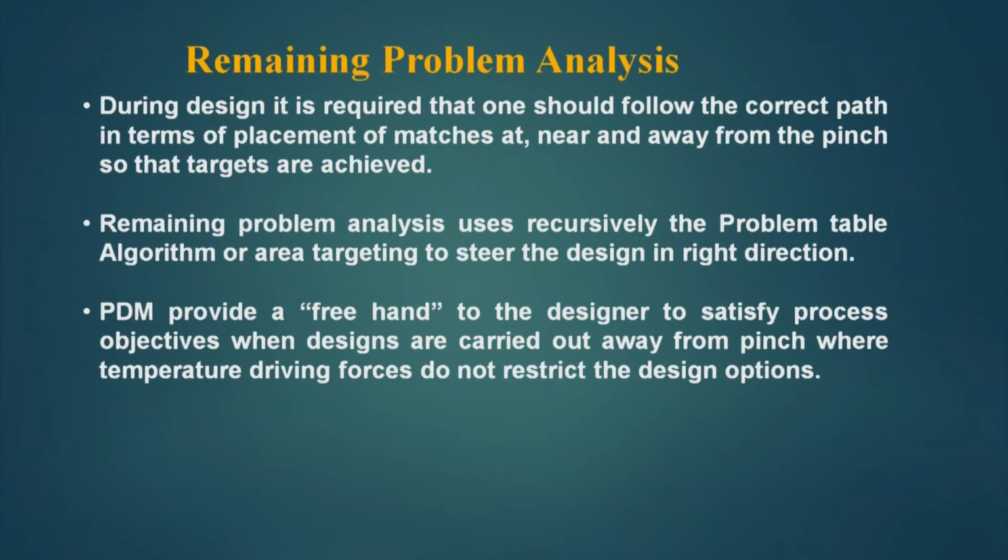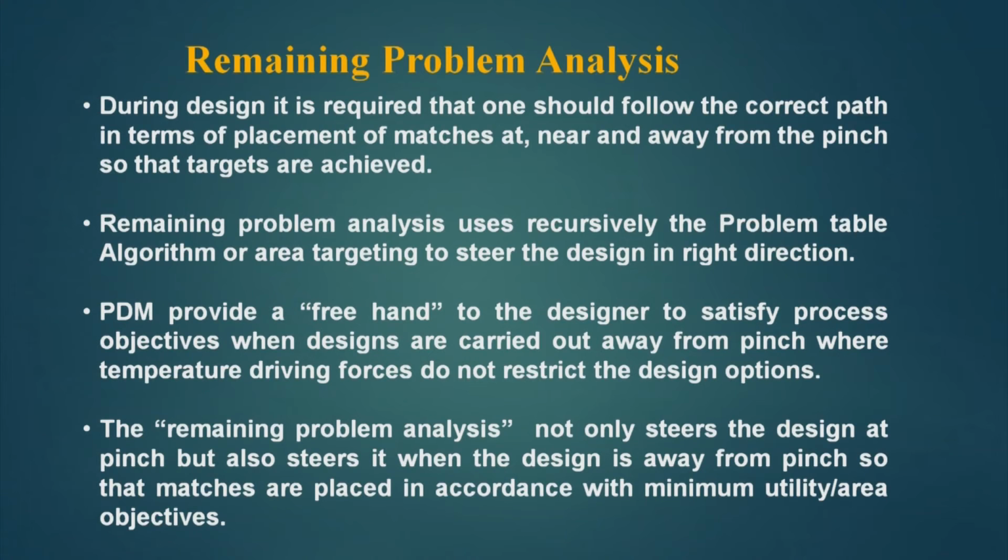But this is not so when we are designing the network away from the pinch. Why? Because away from the pinch, the temperature driving forces are not restricting, and large temperature driving forces are available, as when we go away from the pinch, the temperature driving forces increase. The remaining problem analysis not only steers the design at pinch, but also steers it when the design is away from pinch, so that matches are placed in accordance with minimum utility or area objectives.